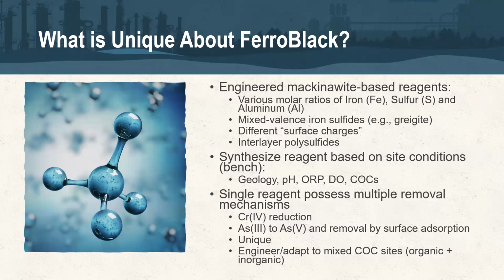So we've mentioned a few things that make this type of product unique. Again, the synthesized product that we're injecting here is FerroBlack. Probably one of the most important things to me, which I just mentioned on the previous slide, was the bench-scale testing and treatability. Again, because geology is so different site to site, things like pH, ORP, DO, not just the contaminants of concern you have, but maybe even some tertiary contaminants that are not targeted for you, or even just naturally occurring additional metals or geochemical conditions that we need to assess and design for. That may be part of the overall reason to do a bench-scale treatability.